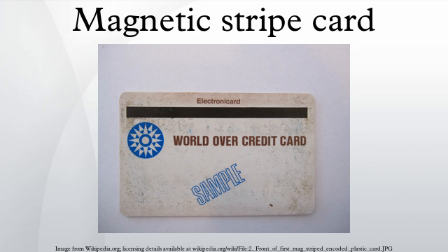Magnetic stripe cloning can be detected by the implementation of magnetic card reader heads and firmware that can read a signature of magnetic noise permanently embedded in all magnetic stripes during the card production process. The signature can be used in conjunction with common two-factor authentication schemes utilized in ATM, debit retail point-of-sale and prepaid card applications. Counter-examples of cards which intentionally ignore ISO standards include hotel key cards, most subway and bus cards, and some national prepaid calling cards in which the balance is stored and maintained directly on the stripe and not retrieved from a remote database.